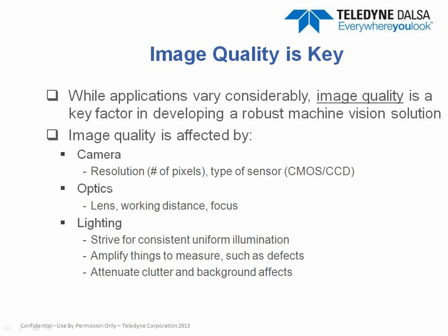Lighting. Again, as I mentioned before, strive for consistent lighting, that amplifies the objects that you want to inspect for and attenuates anything in the background that you don't care for, so you get that reliability in the vision application.